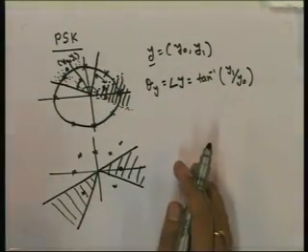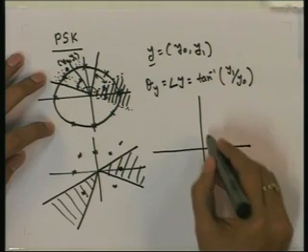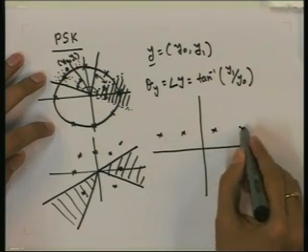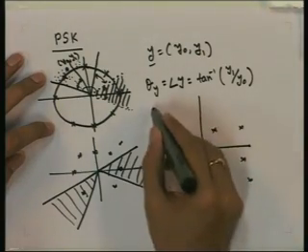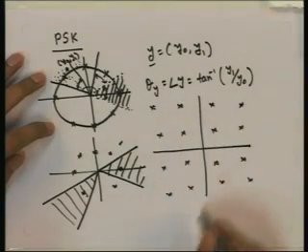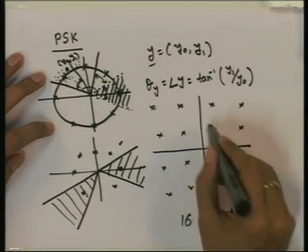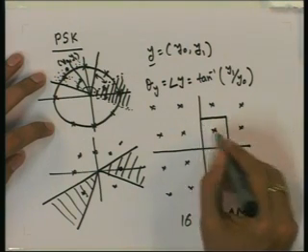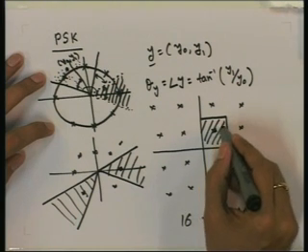Okay. So, talking about decision regions, what are the shapes of decision regions for example, QAM? So, if you have 16 QAM constellation, what are the decision regions? This is the 16 QAM constellation. What is the decision region for this? This is the decision region. We can see that if the received point is in this region, then this point is the nearest to that point.